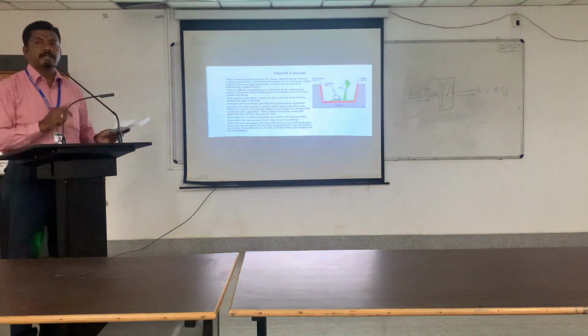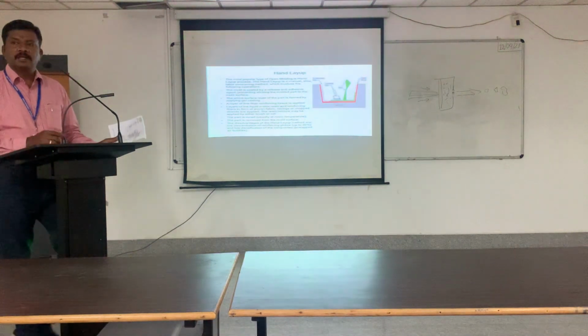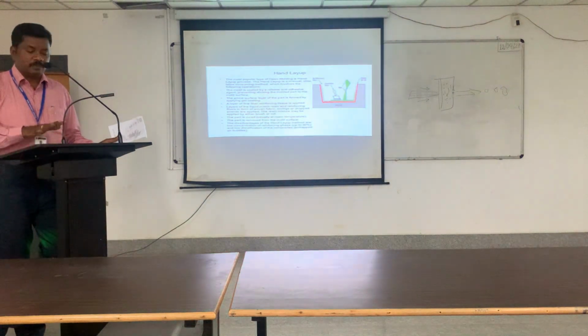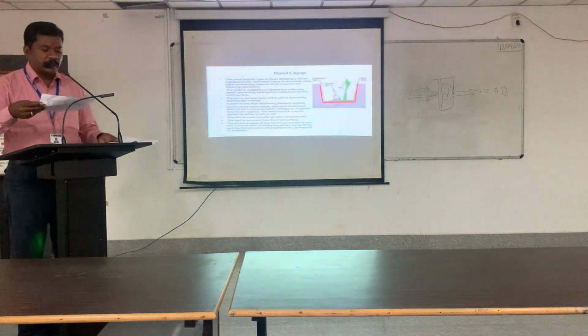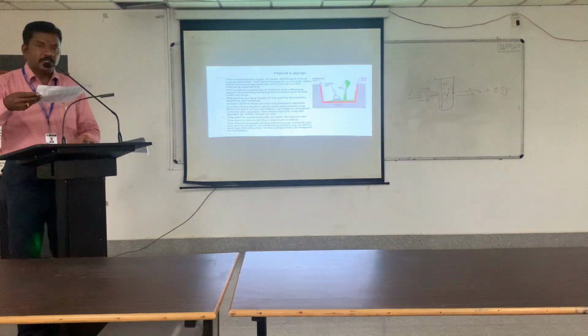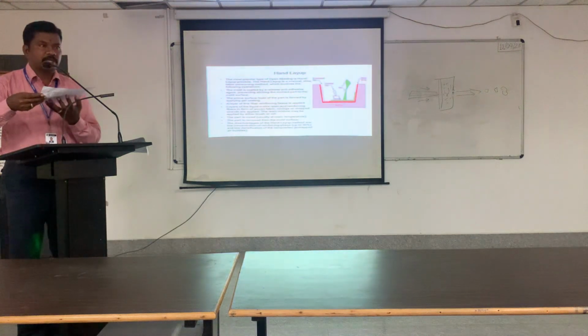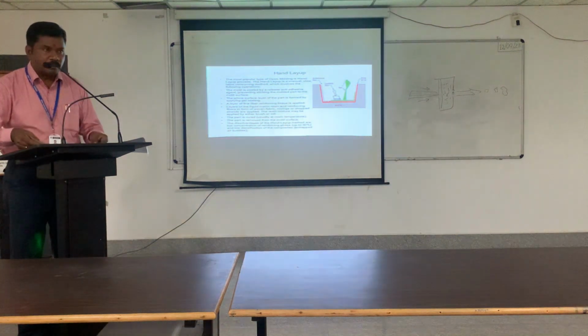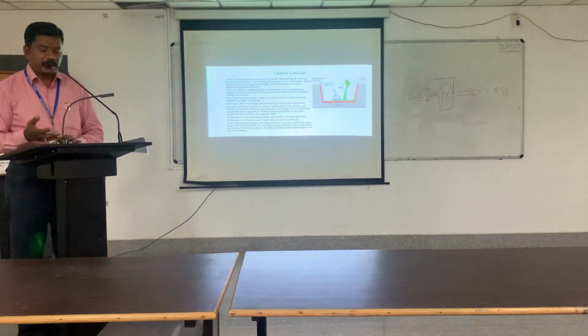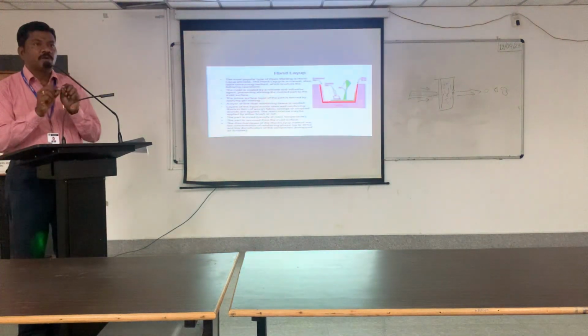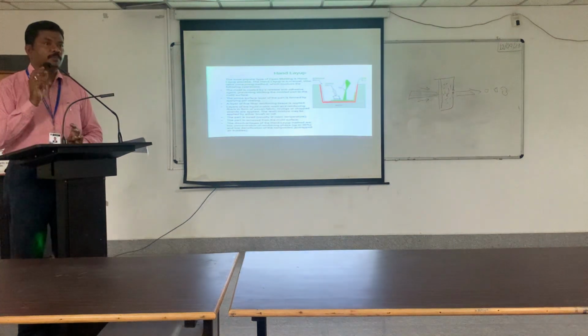Initially you have to cut the reinforcement mat, and the first layer you have to put it. Once you put the layers, it will not completely wet out. Okay. During placing of the first layer, in between the layer and the surface, some amount of atmospheric air will be there. Sometimes that will also be clogged between the layer and the surface. So that has to be taken away. Otherwise, some holes will be created. That will be called pores.